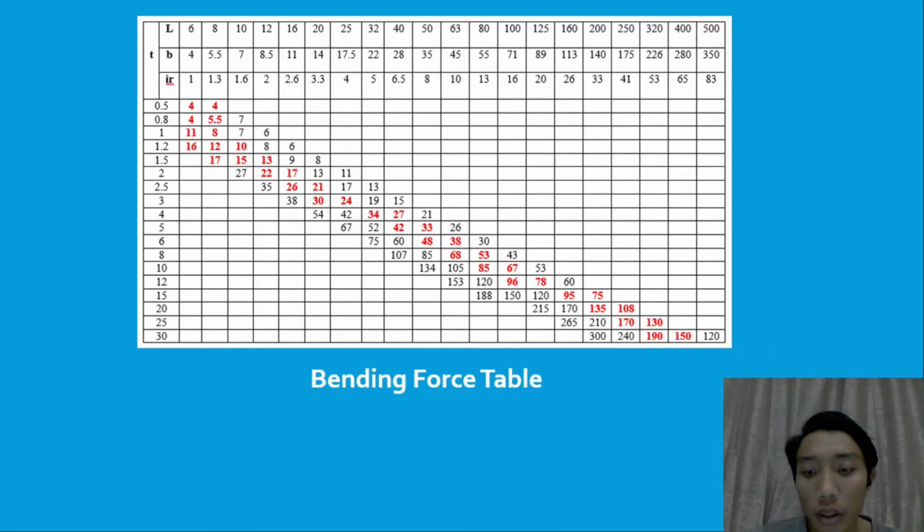I can now see that the minimum flange length is 0.5 mm for such a bend, so I have to keep it in mind when designing. The required die width is 12 mm and the tonnage per meter is 22. The lowest common bench capacity is around 100 tons. My workpiece bending is 3 meters, so the overall needed force is 3 times 22, equal to 66 tons. Therefore, even a simple bench with enough room to bend 3-meter pieces will do the job.